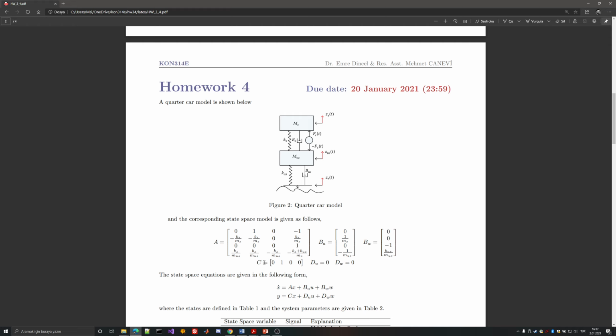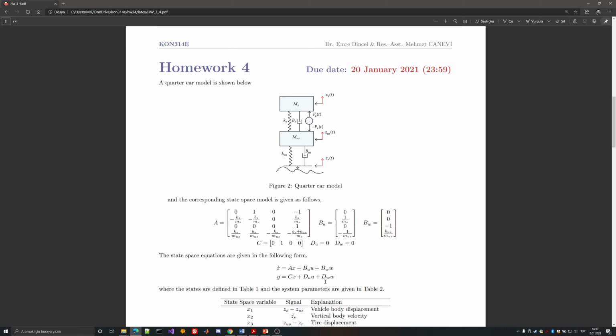And we are looking for the second state in the state space representation here. You are given the state space representation, so basically our system model looks like this. You might recognize the A, B_u, C, and D parts here, but if you have disturbance in a system and if you're using the state space representation, you can immediately see that we have another input, which is namely the disturbance, and it is basically the same as u.